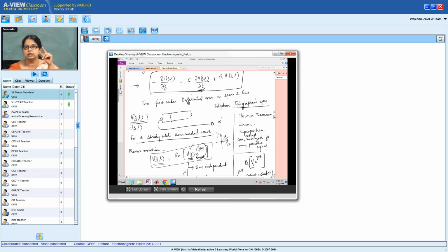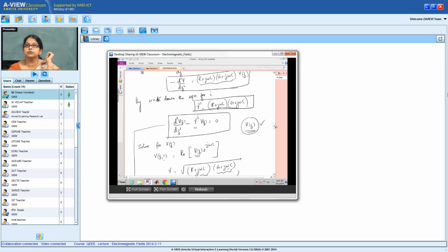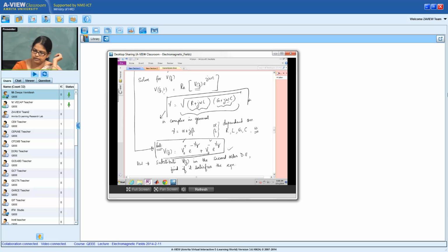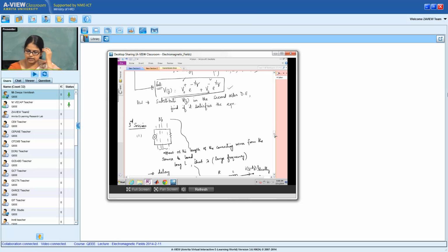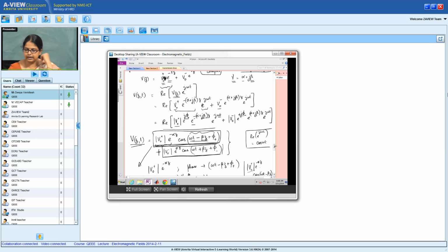At some stage we said let's work with a sinusoid, a single frequency, so that things become easier, and we used the complex notation, and worked out the differential equation for the propagation of voltage. This equation does not have time because we know how it is going to vary as a function of time, because it's a simple sinusoid. And we had this definition here, which you need to remember, gamma, the propagation constant. And we realized that the solution is the sum of two waves. That's what we reached the last class.